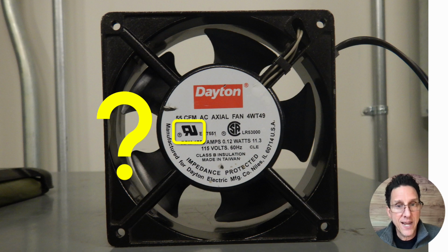And this fan on the screen there, that's part of a VFD. So it's a recognized component for that VFD, right? Generally, that's what a UL recognized component is. Not the same thing as listing or classified. It's lab tested, but it doesn't really meet the same requirement as satisfying code, as far as listing or labeling. But it is recognized by UL.